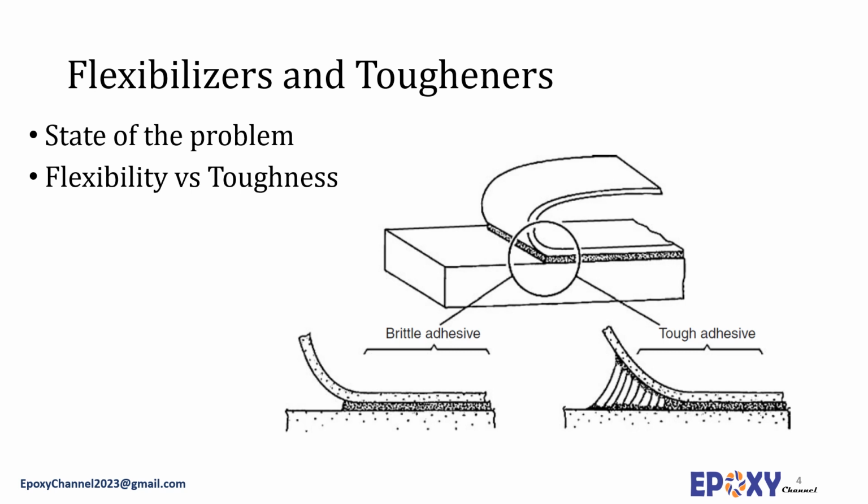Epoxy resins suffer from brittleness and have poor resistance to crack initiation and growth, resulting in poor impact and peel properties. In sealant formulations, epoxy resins do not often provide the desired elongation, and so properties such as flexibility and toughness must be improved. These problems can be overcome by either flexibilizing the epoxy structure or incorporating modifiers into the adhesives.